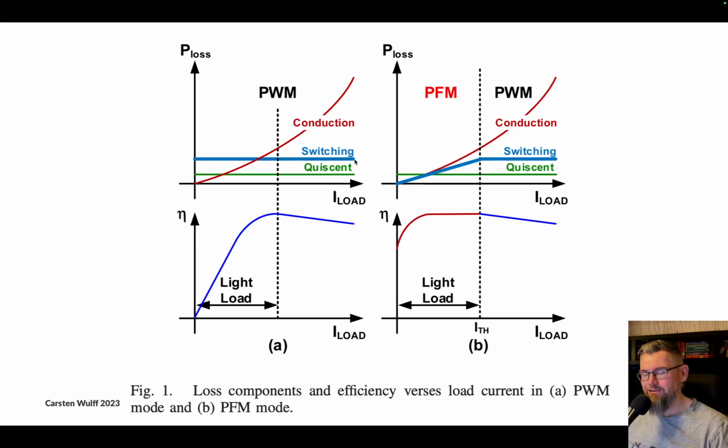That will have some capacitance, you will have some switching losses, and those matter for a while, but the PWM can deliver a fantastic amount of current very efficiently. But if the load is very low, so if your average current is really, really low, then those switching losses matter. And that's where PFM is better. So it's better for light load scenarios.